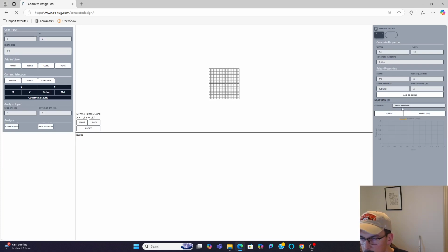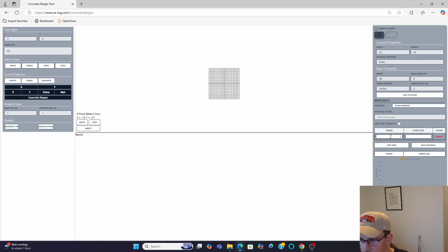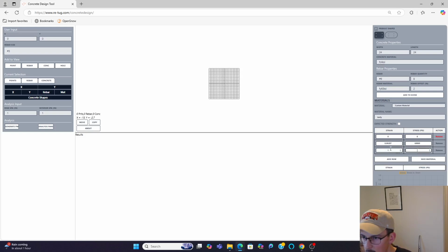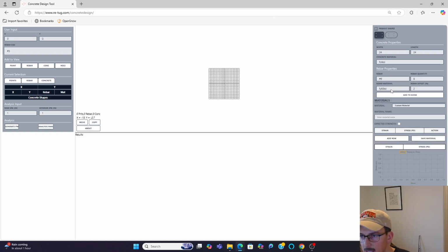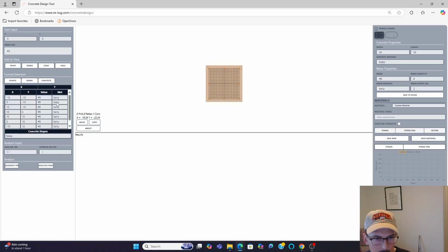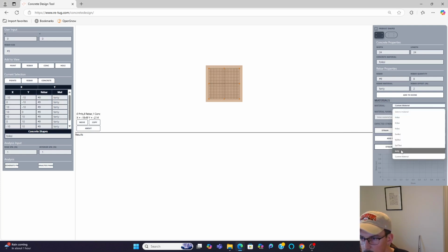In order to make a custom material, you come in here, custom material. Let's give it a name, T only, and we'll do this. We'll say 60,000, one, and we'll say it starts to break at that point. Okay, so that's been added, and then to apply that, you click on T only, and then window over it, and you can see that's the material that's been set. So this now only has tension capacity, no compression capacity.